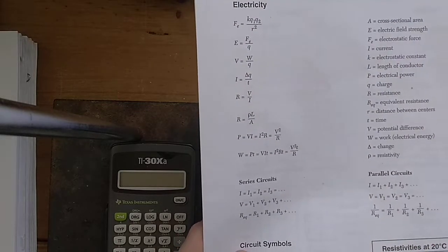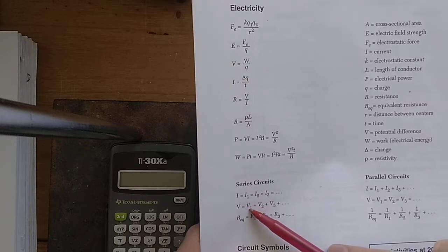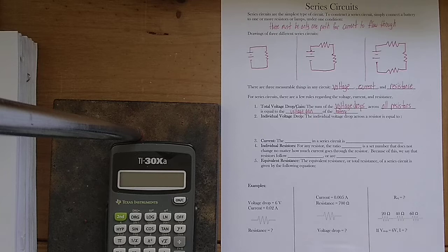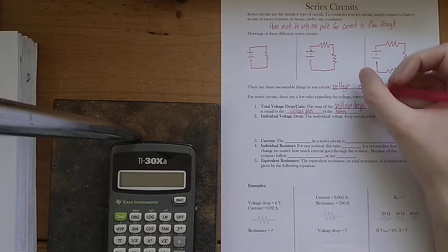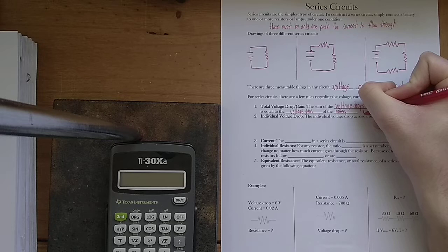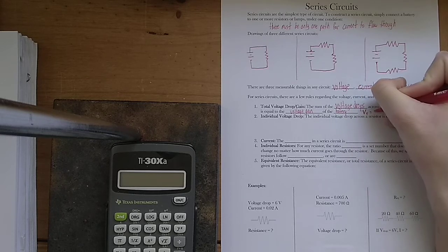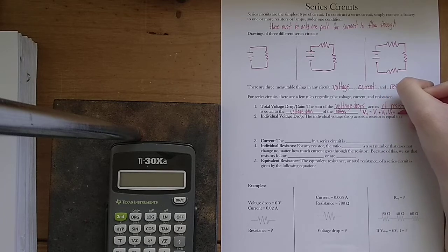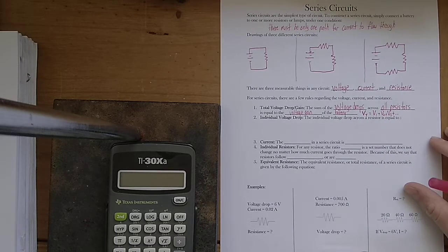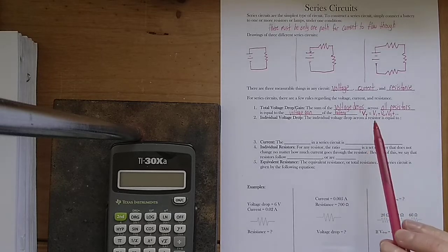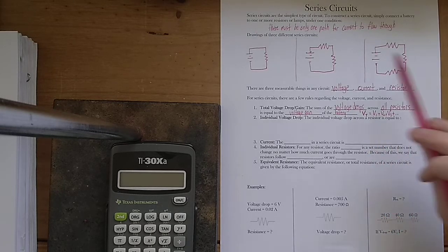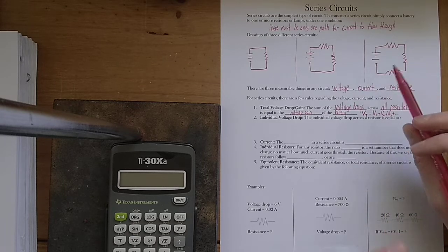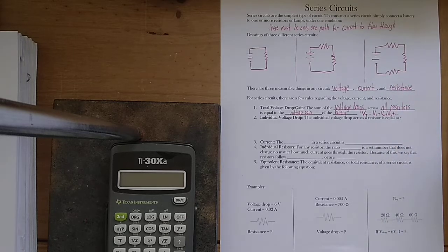And the equation I want to draw your attention to right now is this one. V equals V1 plus V2 plus V3 plus ... That might just seem like kind of a random thing to write, but this is what it's referring to, the total voltage drop or gain. So what I like to write is Vt for V total equals V1 plus V2 plus V3 plus ... That is your reminder in the reference tables of how the voltage drops for different parts of a series circuit work when we have a series circuit, and how they compare to the voltage gain or the total voltage of the circuit or the voltage gain of the battery.